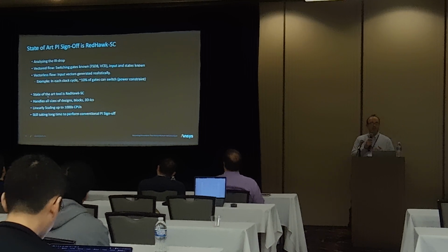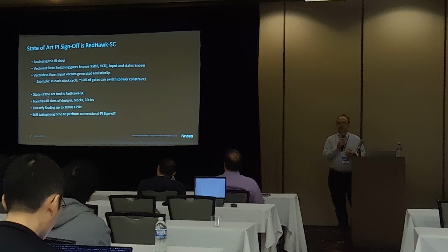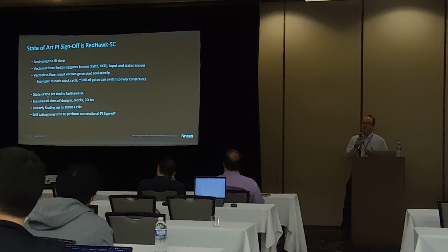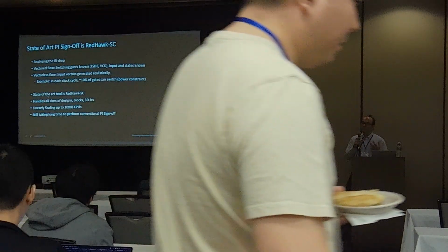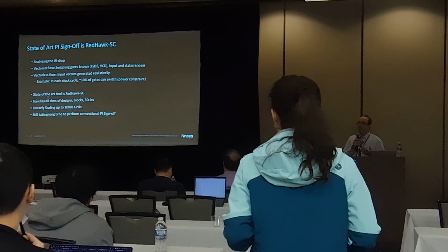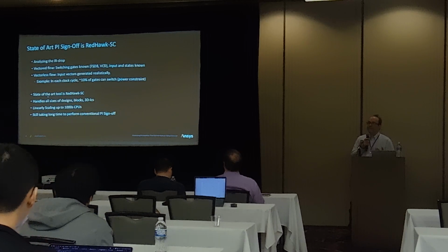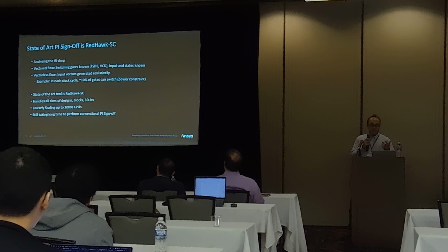We have many different sizes of designs, small to large ICs. Our tools, and our competitors' tools are very good too, can scale up to many, many cores. The problem size is bigger, as you might imagine. If you're solving a system of billions of nodes, you can hardly solve it in one system. You need to distribute the problem using solver techniques. But we have good linear scaling as we go to more CPUs. Our customers are able to run on thousands of CPUs.